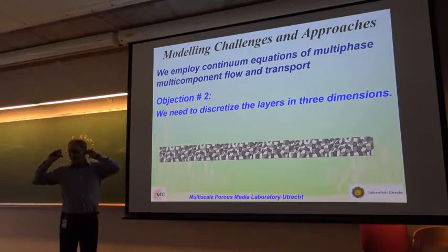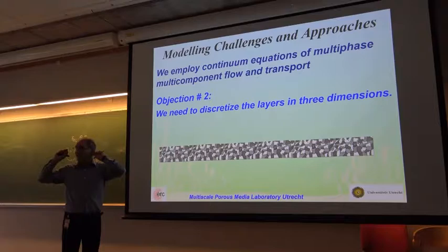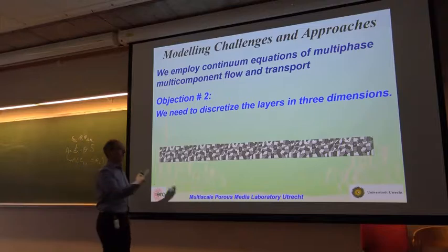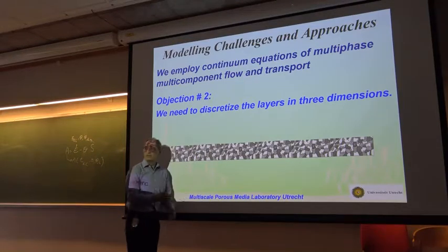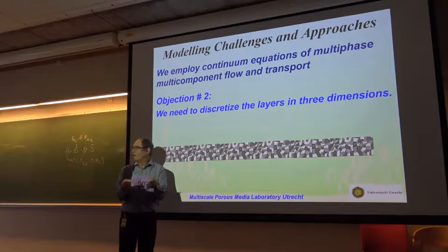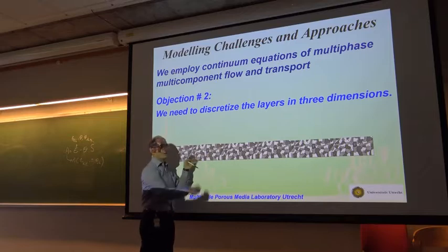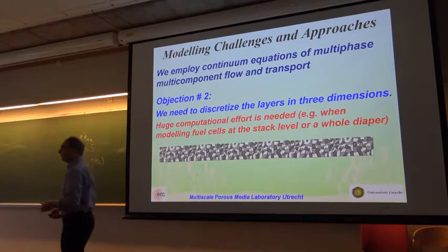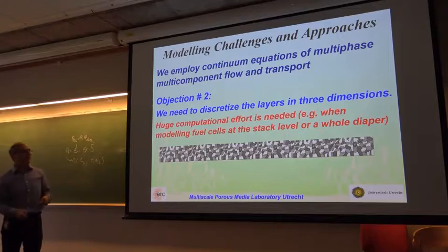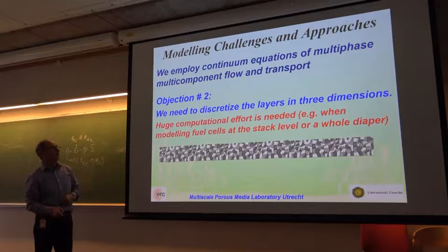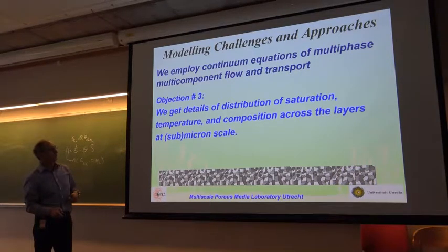Are the numerical experts here? Is that the case? I think you might get this excess diffusion along the paper more than across it. Right. So it can give you numerical artifacts. Yeah. So the remedy is in this direction to also make the grid cells smaller, okay, maybe 5 times the other size in that direction. That means you need a huge computational effort because the grid cells should be very small to match this size in that direction. So that's a huge computational effort.